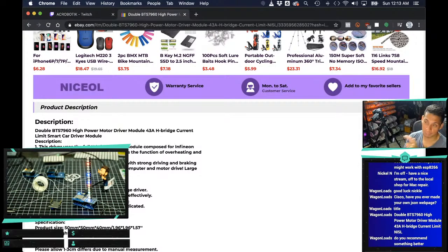I do that a lot. I'm doing that with the LEDs. Those NeoPixel WS2812B LEDs are supposed to work off of 5 volts. I have 5 volts for power, but I'm using a 3.3 volt signal for data, and that works just fine.